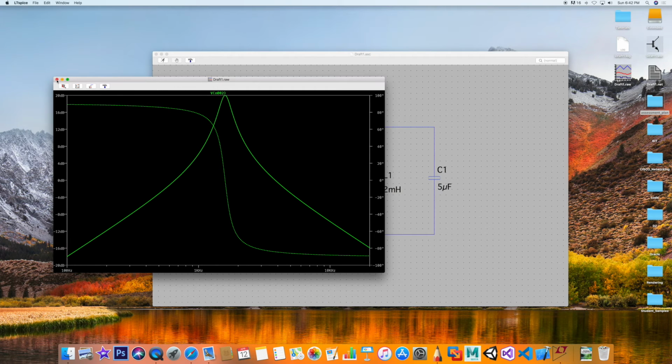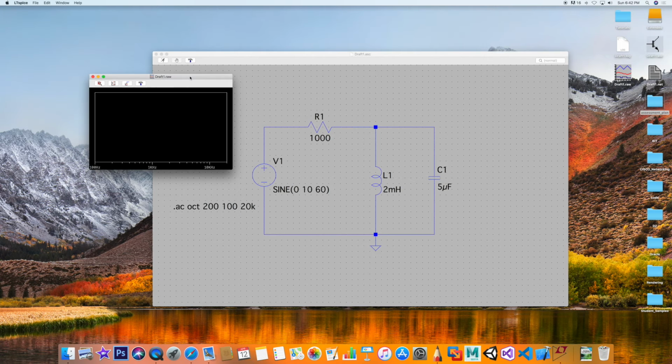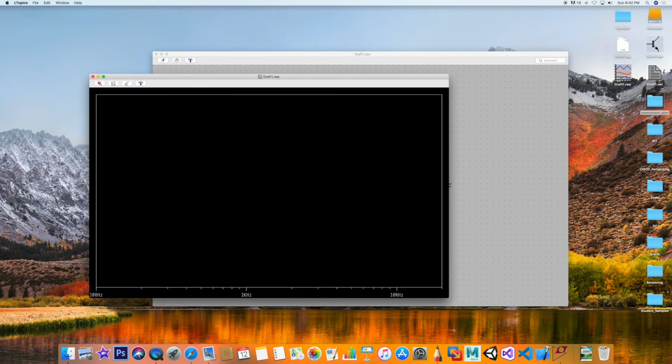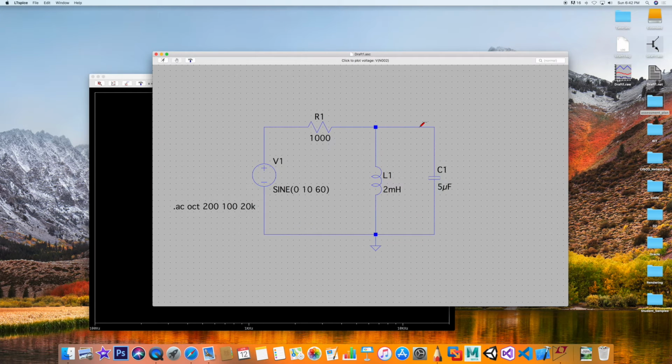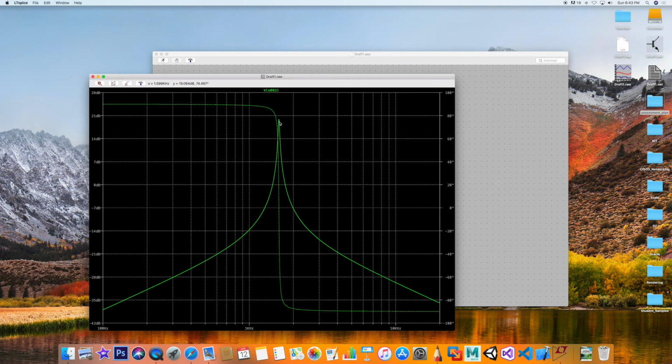Okay, all right, well, let's increase it even more. Let's make it 1,000. 1 kilo ohm. Right, let's run this again. Let's see how that curve or that bell curve reshapes itself. So I'm going to just select the output here. And there you have it. Okay, so again, the angle shifts. So let me just go ahead and put some grid. The angle shifts right. That means it reaches 0 right at this maximum. And this maximum here happens to be 1.6 or 1.59 kilohertz. Okay?